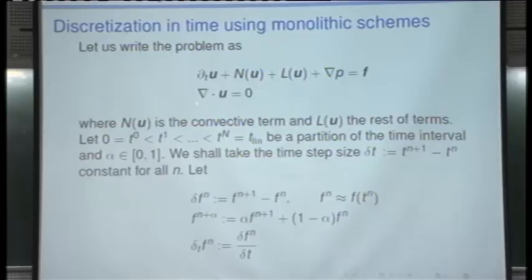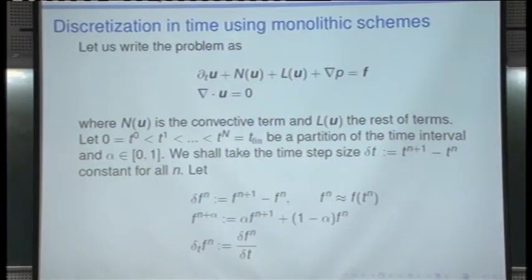Good. Now that we know them, let's first see something easy. Let's relax and introduce the time discretization first. Time discretization of the Navier-Stokes equations. Of course, we are interested in doing numerics, and therefore we have to discretize in space, we have to discretize in time, and we have to linearize because this is a non-linear term, the convective one. But that's easy. That doesn't introduce anything else. So what I will recall here is which are the most important time integration schemes used for the Navier-Stokes equations.